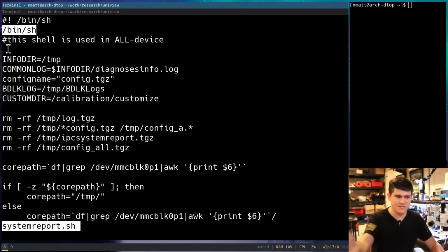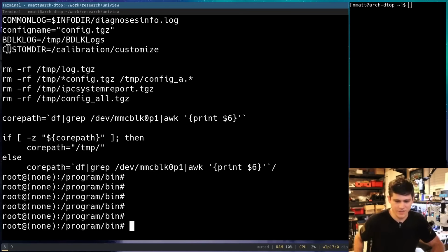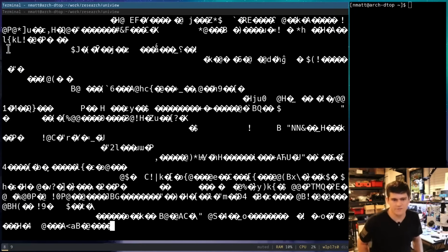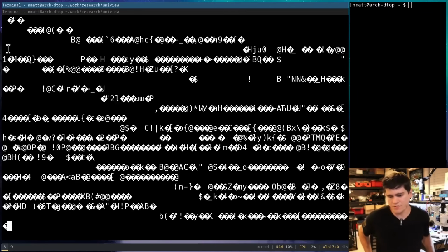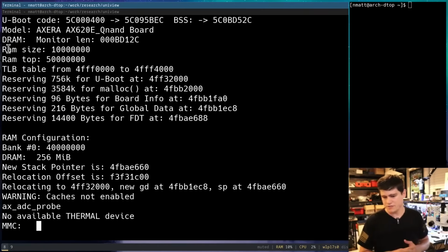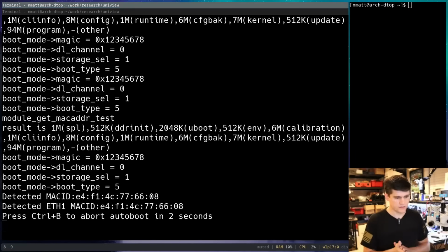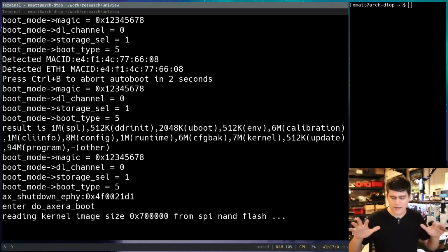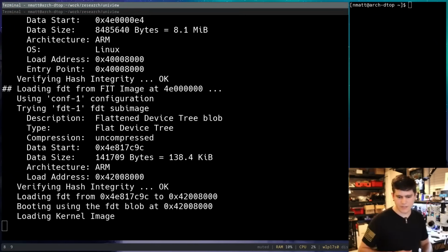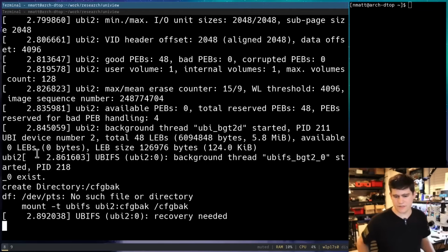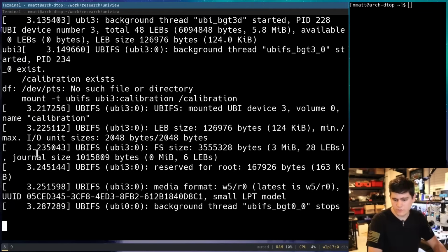So obviously, I've already made the firmware mod on this device. And so we are going to go ahead and power cycle it. Oftentimes when you're in single user mode, reboot doesn't actually do what it should. So, all right, here we go. We're booting up. We're not going to stop the boot process this time. We're just going to let it go. We're just going to spam enter and wait until we can give our input.